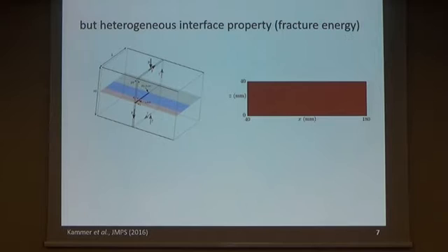It's infinite in this direction because we wanted to avoid these edge effects, to really understand the fundamental underlying phenomenon of the heterogeneity. So what we see is basically this stripe out of here, this length, this width, and here the properties are all the same. We have some linear slip weakening law, as we call it in friction. For fracture, it's basically a linear cohesive law, nothing special. It is a non-zero reference level, but it doesn't matter if you normalize everything out. This has absolutely no effect on the results. It's the same thing. The material property is fracture energy that is like this.